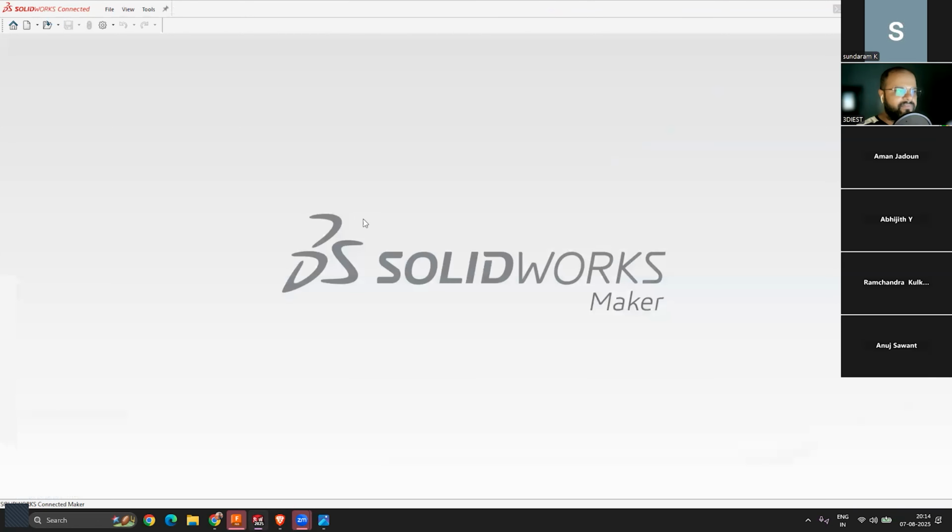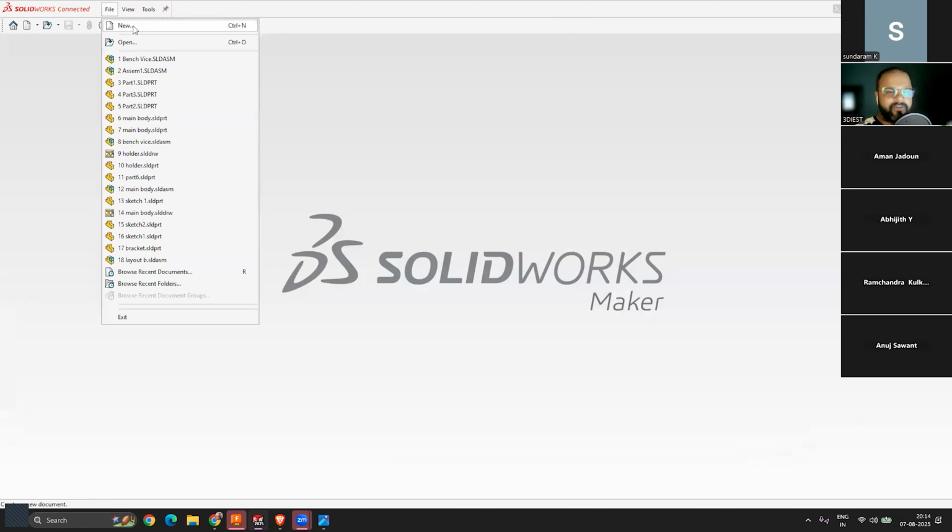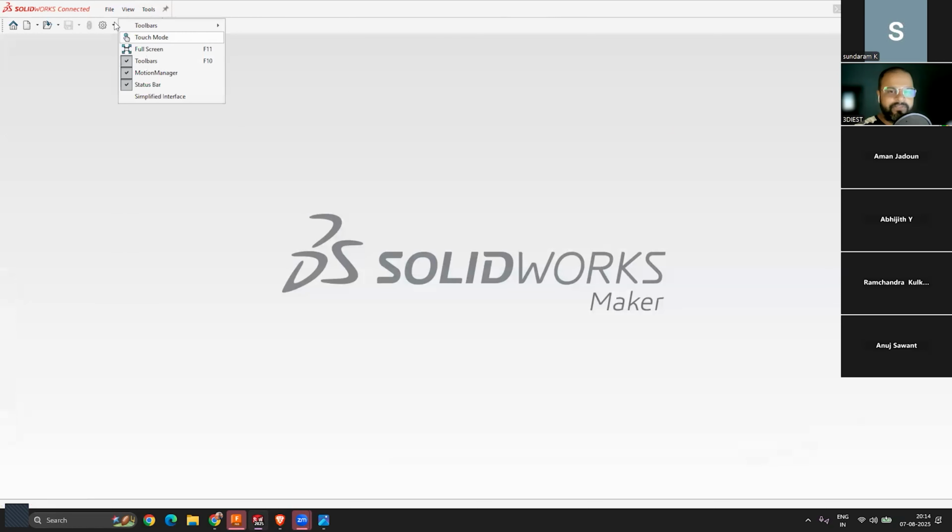Now this is the screen whenever you launch SolidWorks, and let's say you finished modeling all the part files. Now you have to make an assembly using those part files. So how will we do that? Go to the File menu and click on New. We can also use the keyboard shortcut Control+N to launch this command, but here I will simply use my mouse.